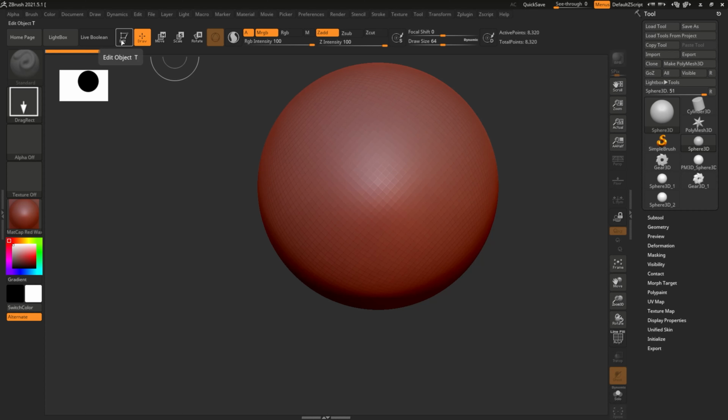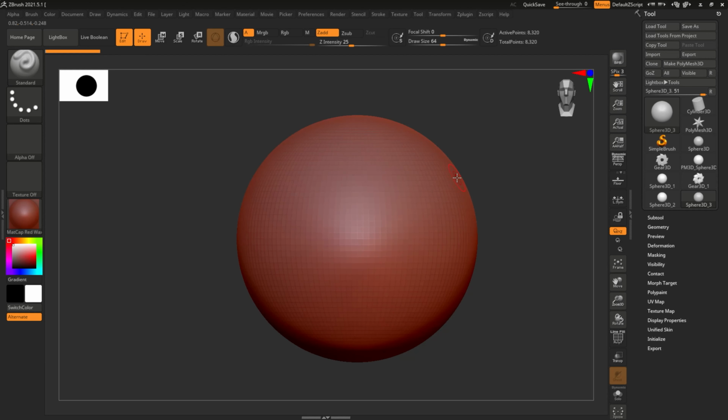There is something to do here, but if you click here, a window like this will pop up. This window is a message telling you to convert to 3D polymesh in order to model. Then, if you look on the right side, there is a tool here, right? You have to press the button called Make PolyMesh 3D on top of this. Once you press it like this, it really is in the form of a 3D mesh. You can see that the conversion is happening and the modification work is possible right away in this way.